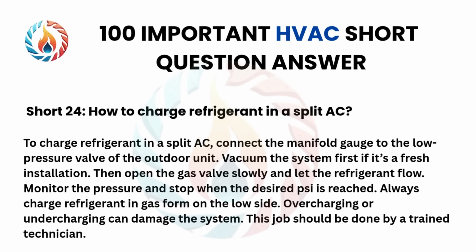Short 24. How to charge refrigerant in a split AC. To charge refrigerant in a split AC, connect the manifold gauge to the low-pressure valve of the outdoor unit. Vacuum the system first, if it's a fresh installation.